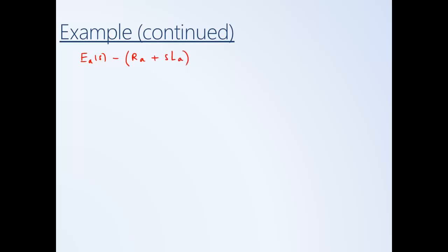And then I substitute in for I sub A. I had JS squared plus BS divided by K times theta of S. Then I had the back EMF KB times S times theta of S. And that's all equal to 0. So now I have a single equation only in terms of our inputs and our outputs. IA has been eliminated. And then I just want to rearrange this into output over input.